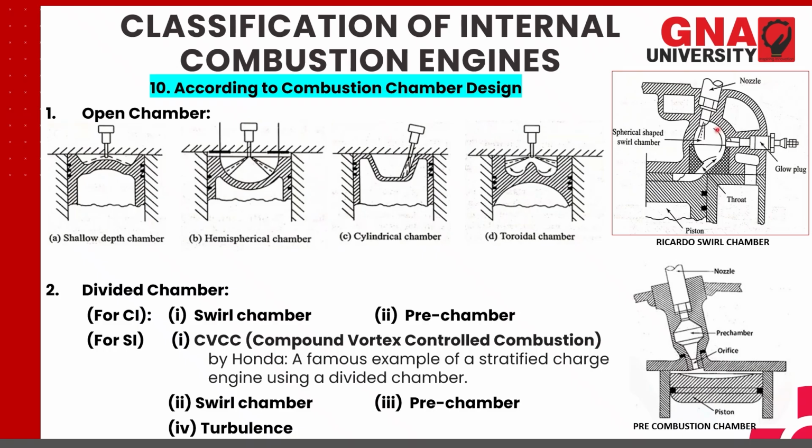So all these chambers help the mixing of air with the fuel, because in the diesel engine the fuel is not injected along with the air, it is injected separately. Hence we need to mix it with the air. That takes place in this divided chamber.